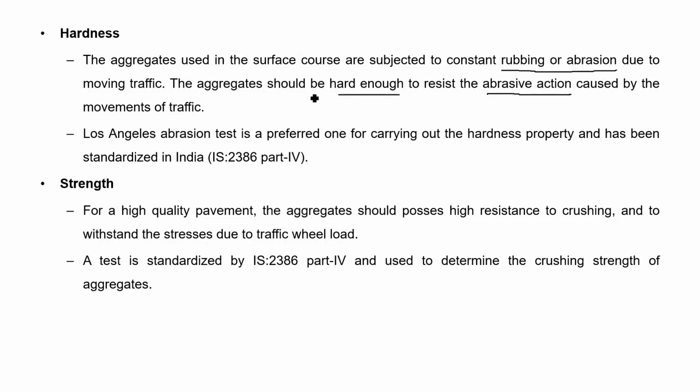And to check the hardness property of the aggregate, the Los Angeles abrasion test is done, which is standardized in India in code IS 2386 part 4.